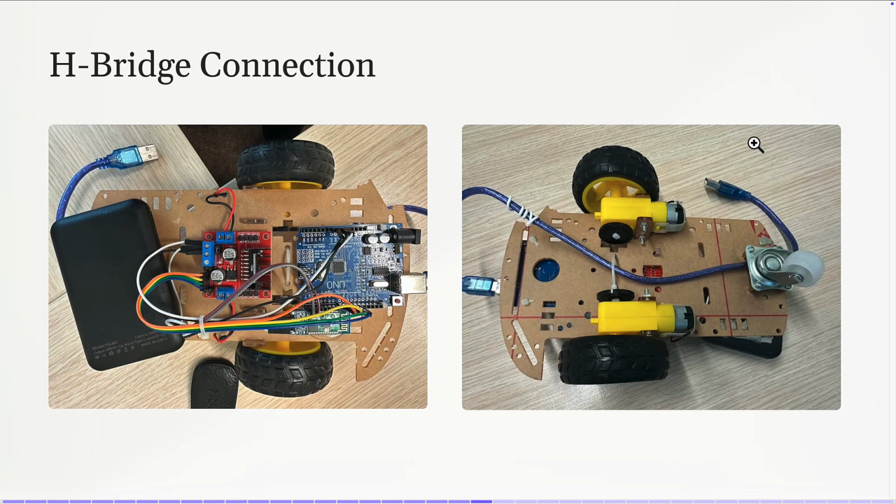Okay, now let's go to Arduino. This is the connection. There are probably a little bit of differences in terms of the pins. Okay, so we have the input voltage that we will provide to the Arduino. We will provide 5 volts because these motors work with just 5 volts. And this is the ground. And this is the 5 volt that we will provide to the Arduino.